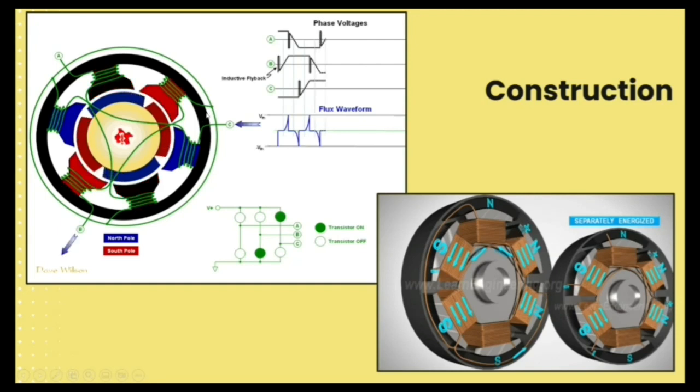We can make the coil stationary and artificially switch the direction and timing of current flowing through them. As I said before, which coil is energized at which time is controlled by the sensors. So it is a huge improvement over DC motors, by using sensors, and it became the brushless DC motor.